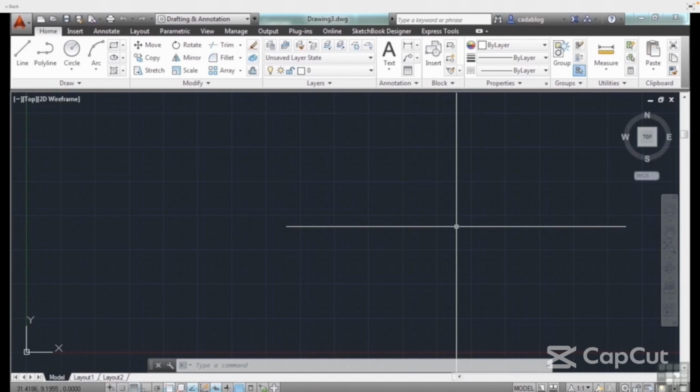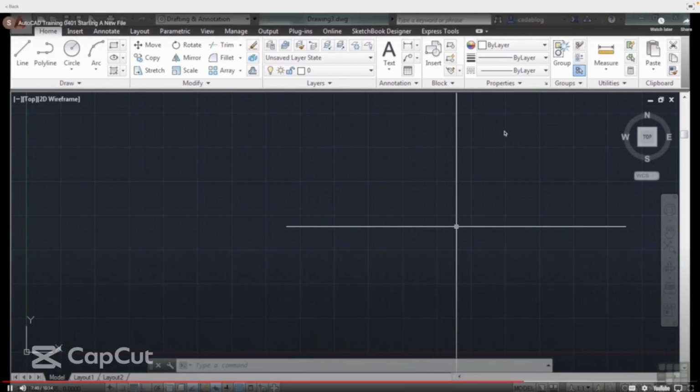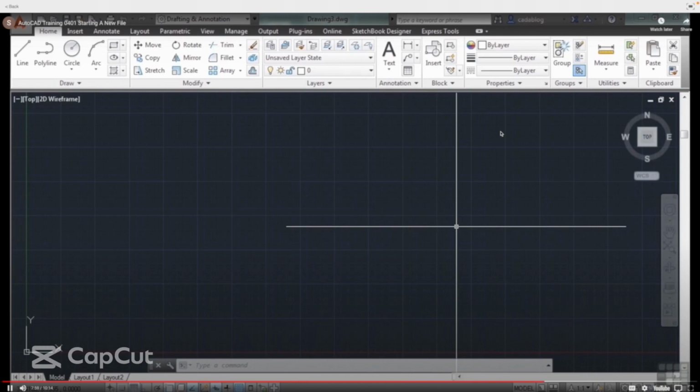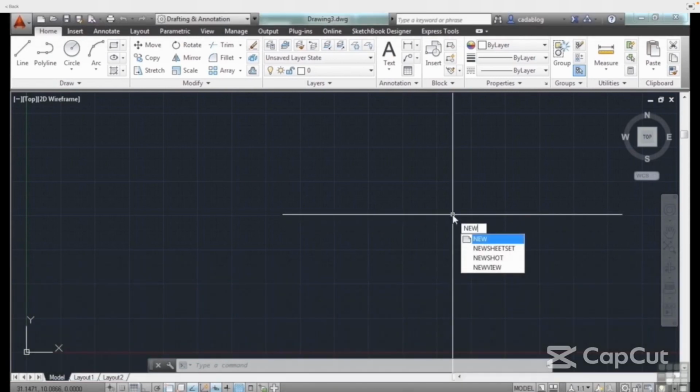Make sure that if you are using a DWG file, you first copy it and put it into your proper folder, or when you open it, perform a Save As immediately. That way you're not working in that template file. That's the nice thing about DWT files. As long as you open a DWT file with a New command, you can't override the template file. So my suggestion is to use a good CAD practice of always using the New command.